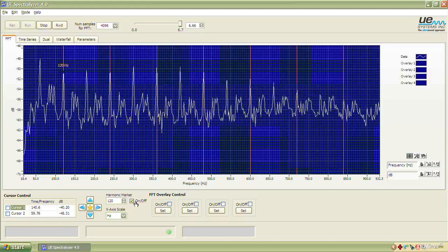Let's say we have absolutely no idea what the fault is. We'll type 0 in here. Actually, you can just leave it blank and not do anything. But bring your crosshair up to the first peak that you see that you think might be repeating itself as a harmonic, and once that crosshair has settled in there, hold down the shift key and then left click.